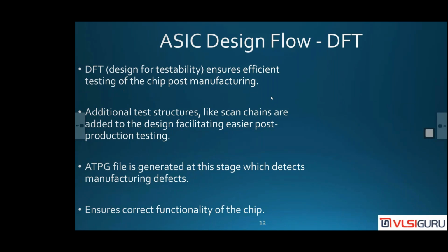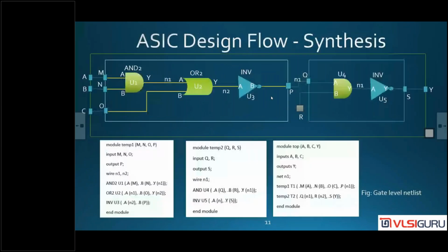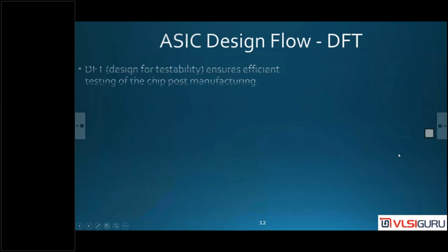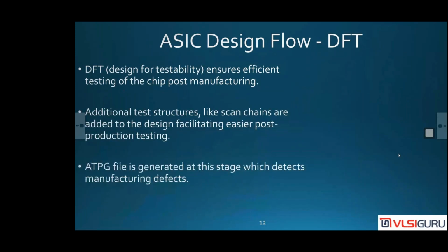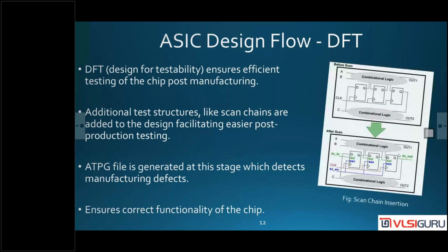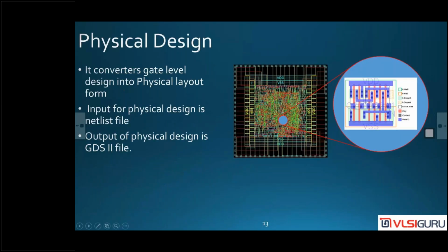From the physical design point of view, as soon as we get the netlist, it will not go directly to the physical design team. It will go to DFT. They will modify the netlist a little bit, but the functionality remains the same. Here and there they will add a D flip-flop, after every few cells, so that they can easily test the chip. That is called scan chain insertion. After DFT modifies it, the netlist will come to physical design.